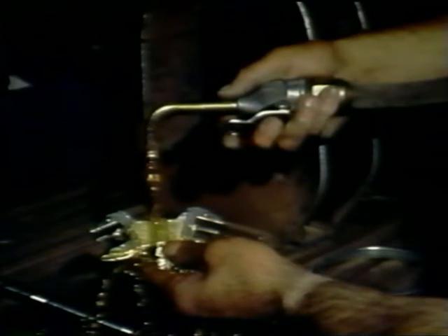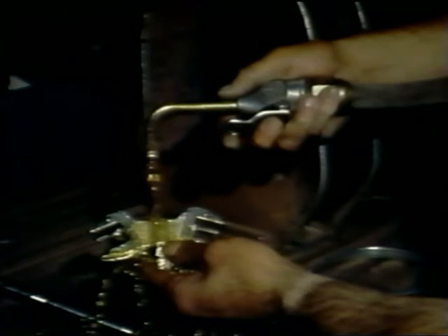Magnetic particle inspection is used to locate discontinuities in ferrous metal parts. The steel parts of the propeller are magnetized by passing a strong electrical current through them. A suspension of fluorescent iron oxide powder and solvent is sprayed over the parts. The particles within the fluid will immediately align themselves with the discontinuity. When examined under black light, a crack or fault will show as a fluorescent line.